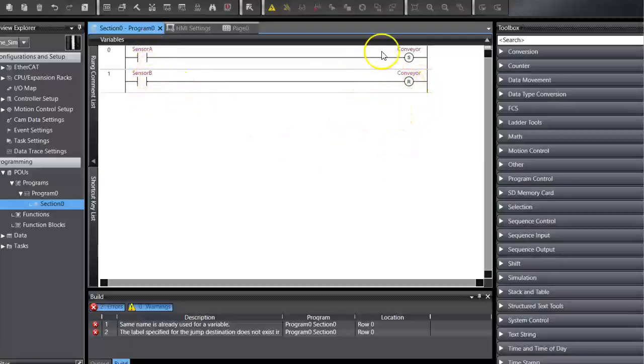Now, be cautious. This is a dangerous sort of situation. Even on an e-stop or power outage, say the power flips off, when the power comes back on, the conveyor can still be set, so it might start up and run right away. You're better off using a start-stop push-button, holding contact type of arrangement, because once it's stopped, you actually consciously have to walk over and start it up again.